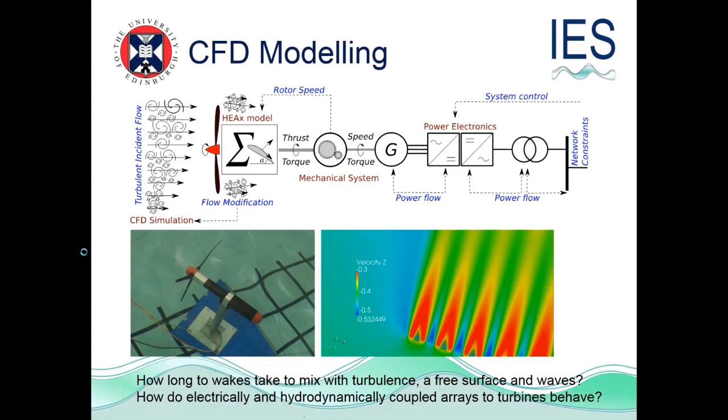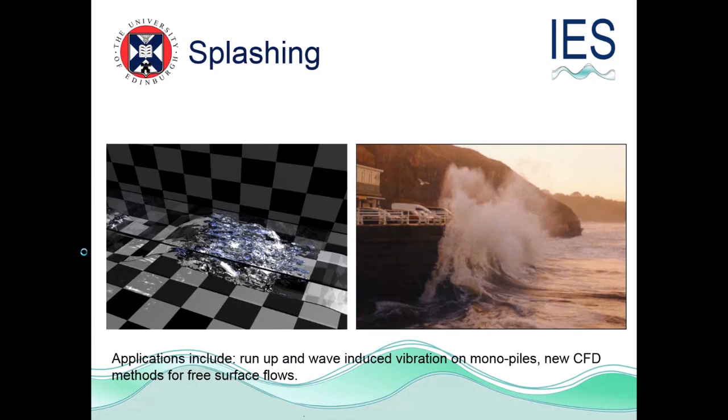And we can then put that into arrays of turbines in a simple channel in this case, and we can look at how long does it take the wake to mix out, what's going on in the flow physics between the wakes as they're mixing, and try and understand what's going on in that kind of thing. So from a CFD modelling point of view, this is the kind of thing where you can have lots of fun, and more importantly, you can burn thousands and thousands and thousands of hours on that supercomputer at the other end.